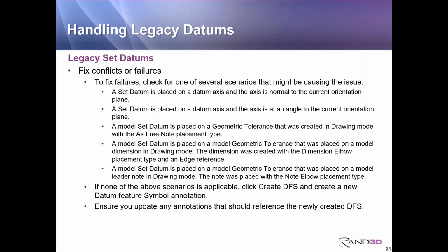You might have a scenario where the model set datum is placed on a model geometric tolerance that was placed on a model dimension in the drawing mode.